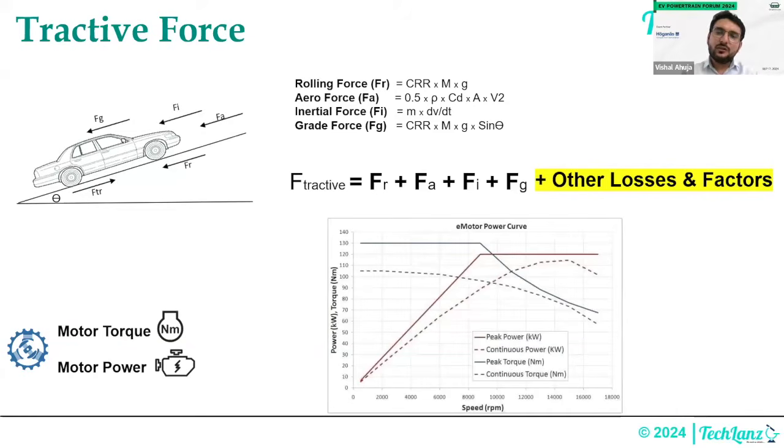Based on that, you also get your rated torque, because the motor torque which is giving the max torque and the max power, these are pulses. But imagine you are going on a ghat road, right? In a gradient condition. People forget that kind of situation when designing the vehicle. Imagine a commercial vehicle trying to climb a gradient, for suppose going from one place to Ooty, or going to Kodaikanal, right? There is a gradient which is continuous in nature.